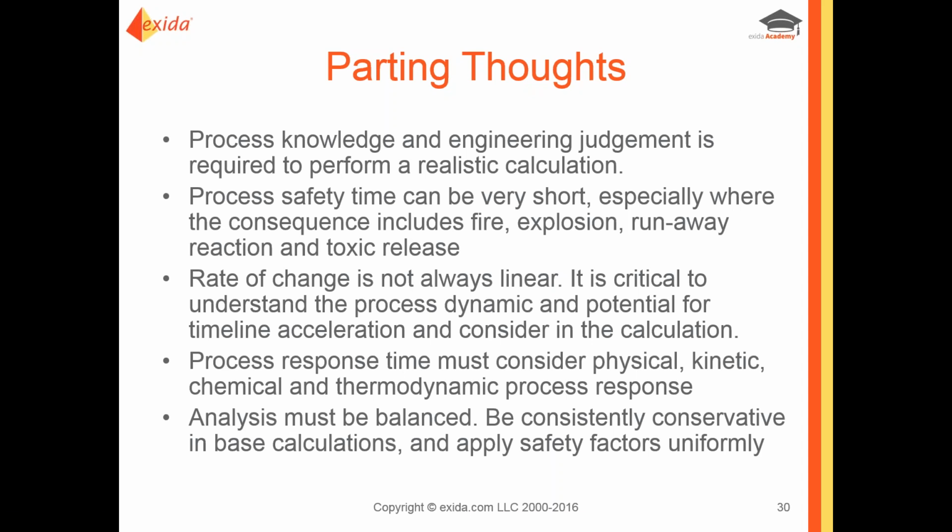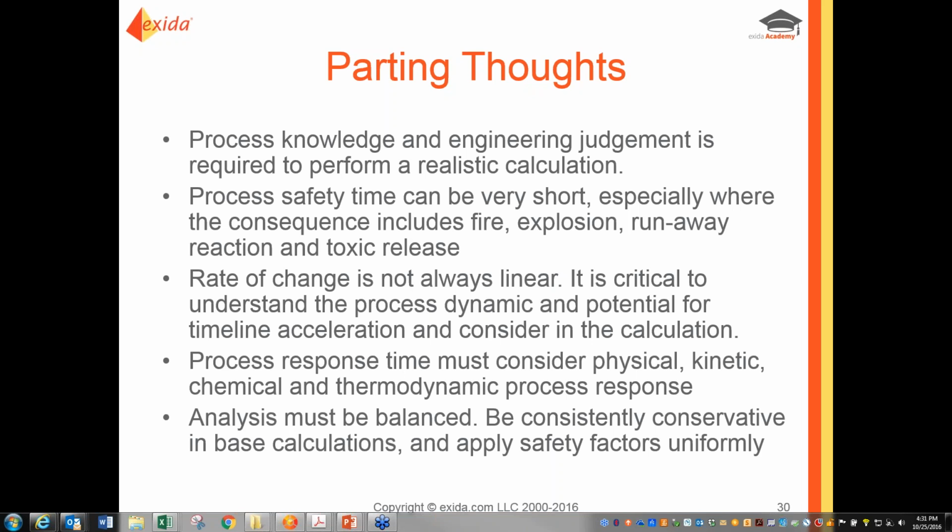We have another question. What about the old rule of thumb that SIF response time should be 1/2 of the process safety time? That is a rule of thumb that has been used, and certainly in those cases where you're talking a fire or explosion or runaway, something that's very fast, using that half rule of thumb is a place to start.